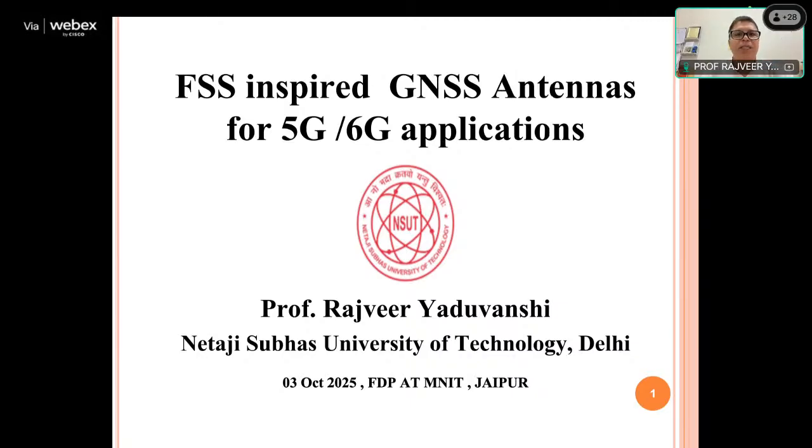So basically, it is a combination of four satellites, and then we are able to get the exact location even in centimeters. So we are designing these antennas for specific use of L1 band, L2 band, L3 band, L4 band, L5 band, the 2.4 gigahertz band, that is Wi-Fi, the 5.8 gigahertz band, that is also Wi-Fi, and for NavIC applications.